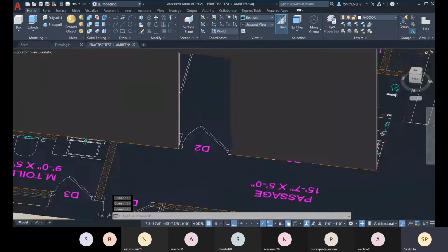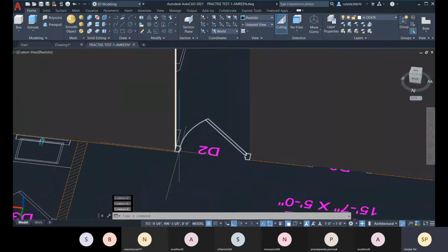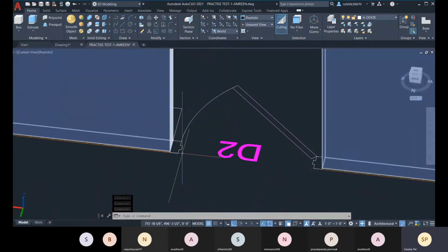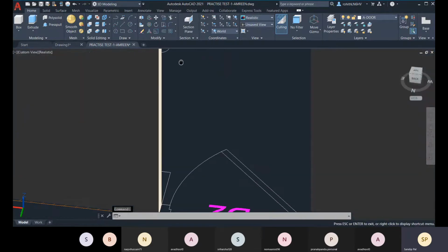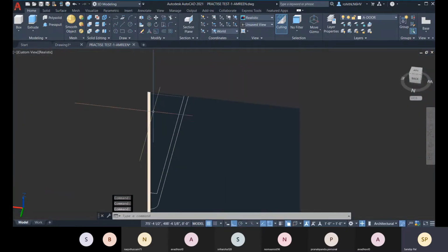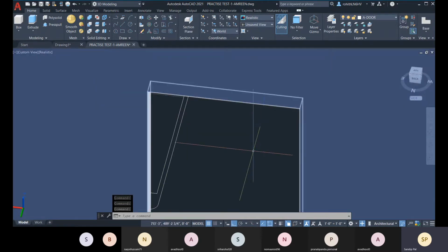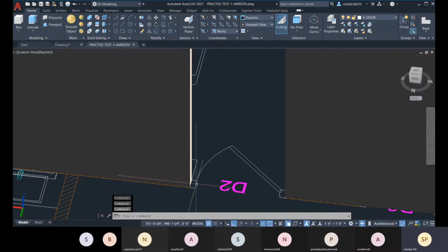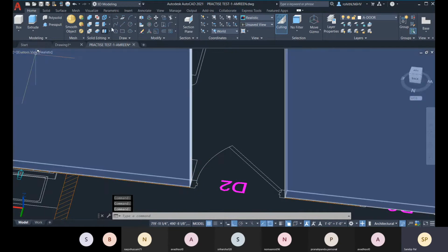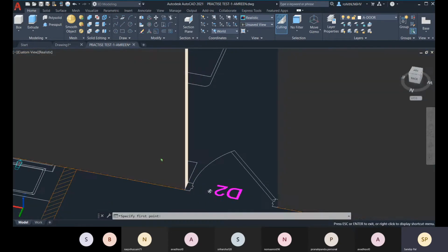It will be really difficult with the extrude option. You would have to extrude it vertically, then create another part for placing it horizontally, and then union it. So there will be lots of steps. With a single step you can make it, so go for fewer steps if you can.